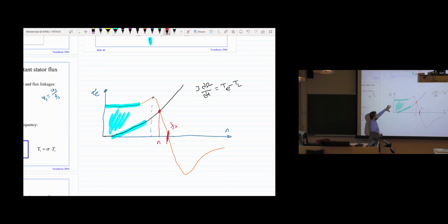So from this torque characteristic, what do you see? That we have this Fs here, and when the speed of the rotor reaches this point, the torque is 0. Therefore, we always need to have Fr with some value, which is Fs minus n. As long as you have this Fr, there's a deviation between these two frequencies, and you'll get some torque, and they look like this. And when we operate a machine, we usually operate in this region. So this is the symmetrical region where we operate the machine, and here is the motor application, and then it's the braking or the generator application. That's what we do.